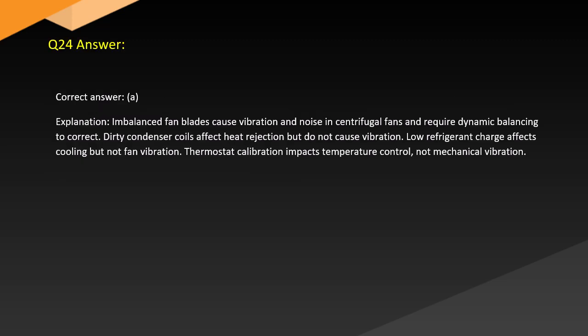Answer. Correct answer: A. Explanation. Imbalanced fan blades cause vibration and noise in centrifugal fans and require dynamic balancing to correct. Dirty condenser coils affect heat rejection but do not cause vibration. Low refrigerant charge affects cooling but not fan vibration. Thermostat calibration impacts temperature control, not mechanical vibration.